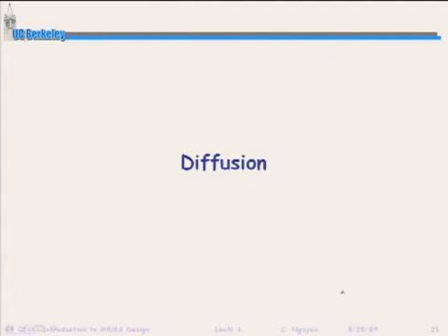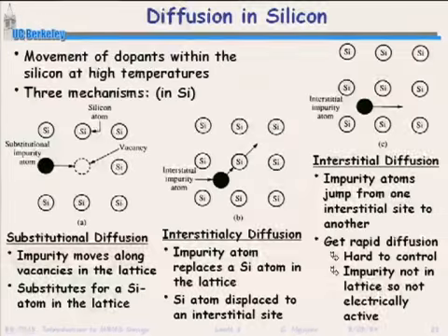So what is this? This is a way for dopants to move in silicon. So you may introduce the dopant through ion implantation or another thing I'll talk about called predeposition, but you'll introduce it in a very shallow layer at the top of the silicon surface. And usually you want it a lot deeper than that. So to get it deeper, what you do is you take everything to a high temperature where the dopants now have a larger diffusivity, a larger diffusion constant, where they can diffuse deeper into the silicon. Okay, so you're trying to make a much deeper amount of dopant into the silicon.